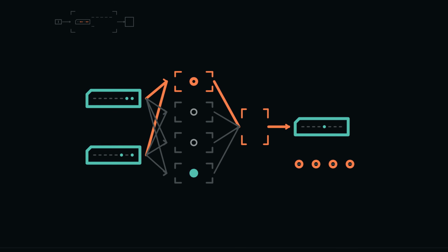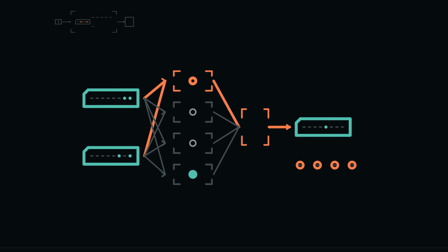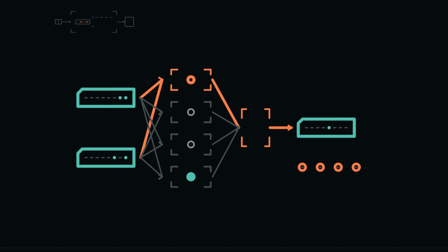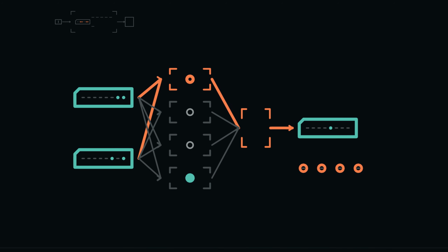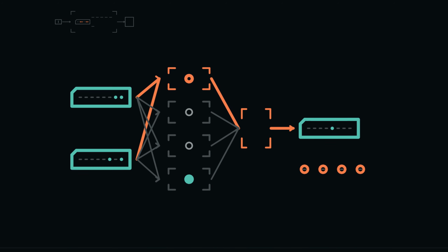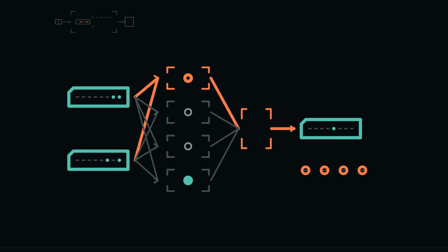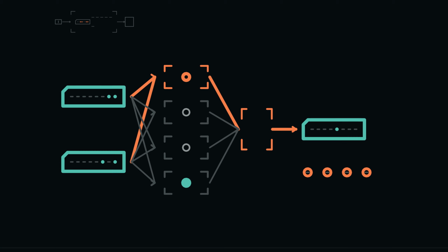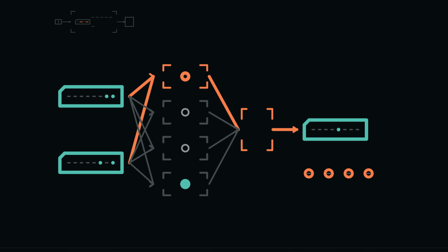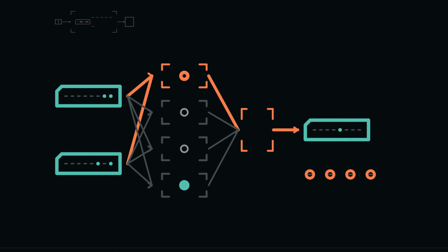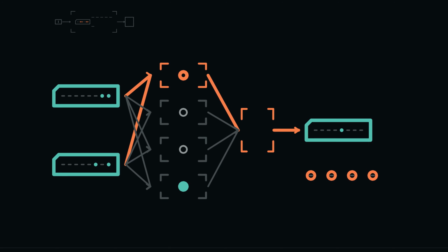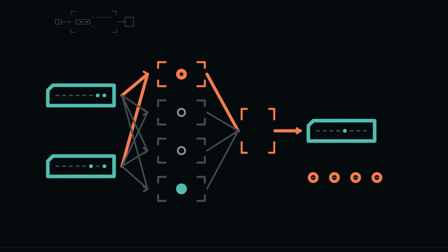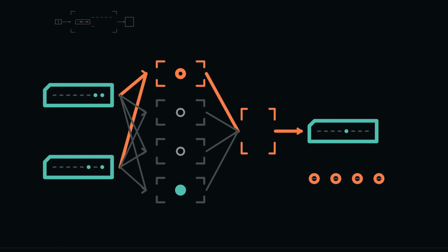Trace 1 operation. R0 holds 3, the immediate operand is 5. The operation field selects addition. Both operands appear at the adder lane, which produces 8 and the corresponding zero, negative, carry, and overflow facts. The output selector accepts that lane. Before the execute edge, R0 still holds 3. At the edge, R0 captures 8, and the flags capture their new values. All 4 are clear for this operation. The root highlight follows selection and commit. It does not imply that other lane outputs became stored results.